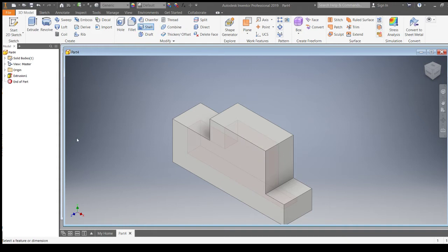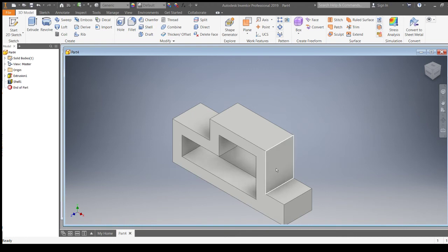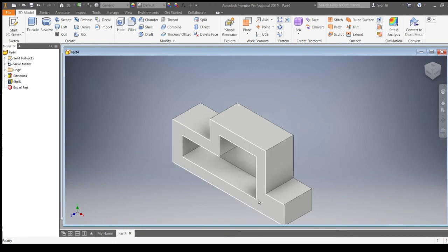So what we can do is we can change the thickness of the shell. Now you'll notice there's a kind of a ghost outline inside of the object. If I change up the measurements of the shell, you'll notice it changes. See, for example, with the 1 millimeter, if I actually were to do it, it would only make a shell 1 millimeter into the object. But we're going to start with a 5 millimeter, so I can properly display this. And then we're going to shell at the front view. So as you can see there's a shell that's just been created, 5 millimeters in.